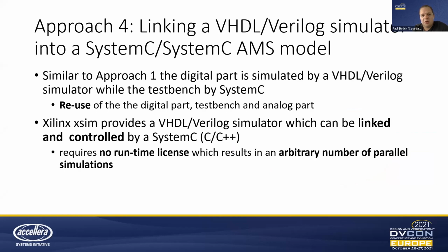And then we come to approach number 4. Can we do something without hardware and speed up the simulation we got from approach number 1? And the simple thing to do is parallelization. And the problem with parallelization is, can we have multiple Verilog simulator kernels running in parallel without running into licensing issues and without interference between each other?